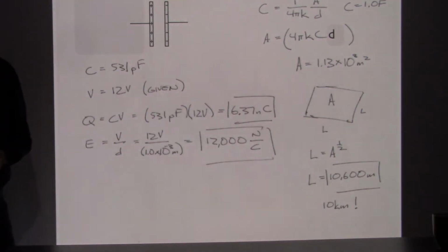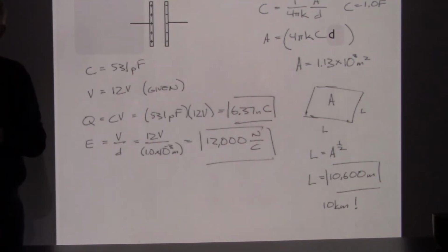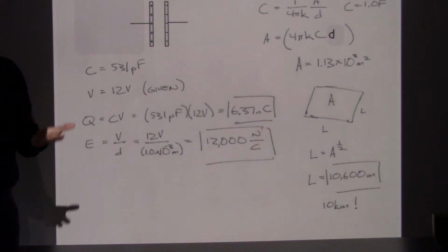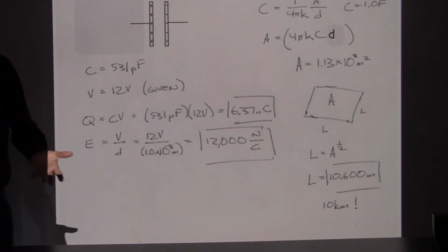In these capacitors, we have a couple of really, really thin conductor layers, and then a really, really thin insulator between them. So the distance is going to get much smaller by a factor of, I don't know, 100, maybe 1,000.